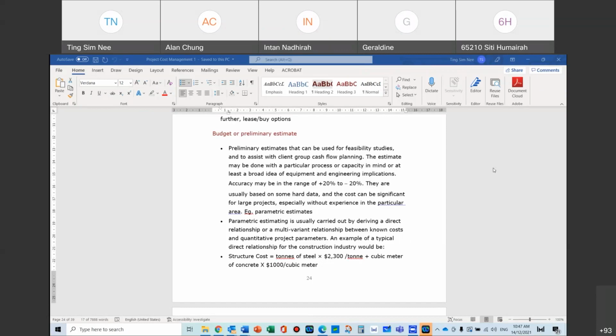Not calculate manpower, not calculate machinery, not calculate material and times it with three rates, not like that. It's just going to be one rate that has basically factored in all these things. It's a very wide range rate, not very specific. So this all-up rate is not so accurate. If we look at all-up rate, we're looking at about 10 to 15% plus or minus, so that is the kind of error that you may have. It's a wide range for all-up.